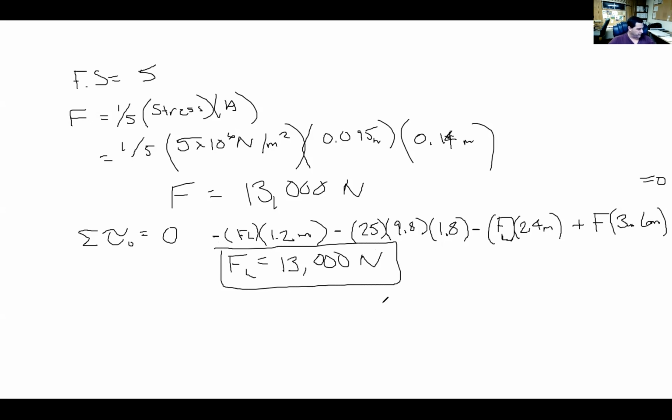But I have two of those, right? One at each location. And they wanted us to figure out what maximum force FL, so that's the 13,000, right? So we have 2, it's 13,000 divided by your 9.8. So each one can support 2,600 kilograms.